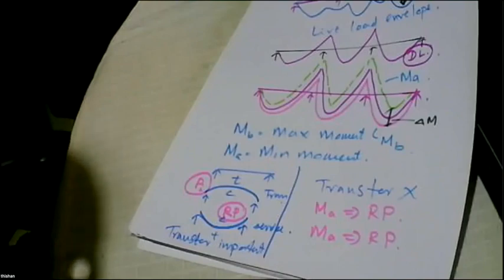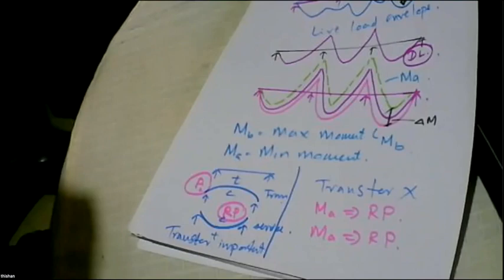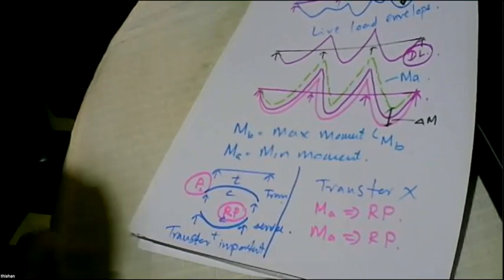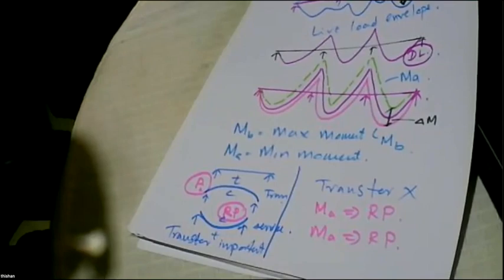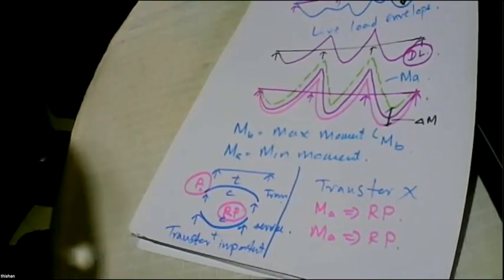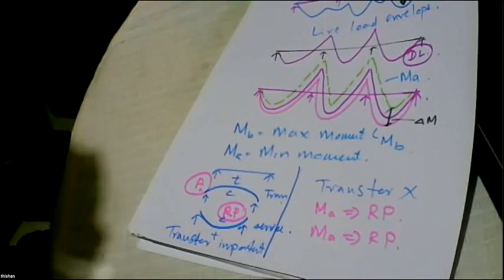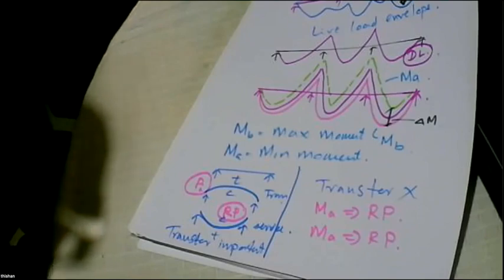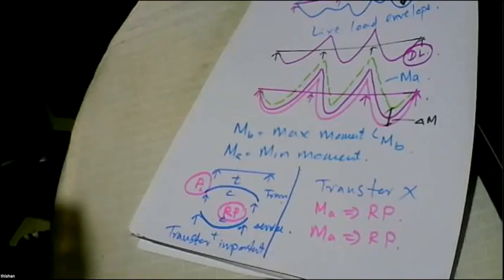Okay, sir. Right. So what you have to understand is, if you take any section, finding the maximum moment and minimum moment at that section is not a big deal. You can just analyze it as a beam in SAP 2000, apply the relevant loads, and get the answer. Pedestrian pavement loads are not going to dominate, because the magnitude is only 5 kilonewtons per meter squared. It's a small load. So you can apply the full load on the pedestrian pavement, that is 5 kilonewtons per meter squared, multiplied by 1.5 meters if they have a walkway of 1.5 meters.